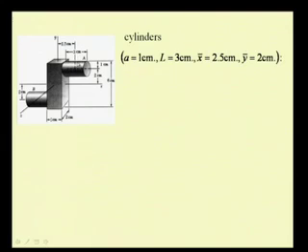So, this is located at a distance of 1 centimeter from this face of the prism, and this face of the prism is located at 1 centimeter from this plane y z, because we know that this total dimension is 2 centimeters. So from this we know these various quantities, say L, a, x bar and y bar, from the geometry that is given.